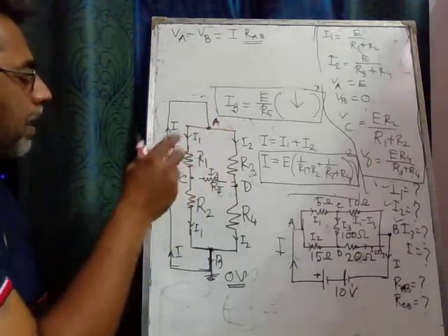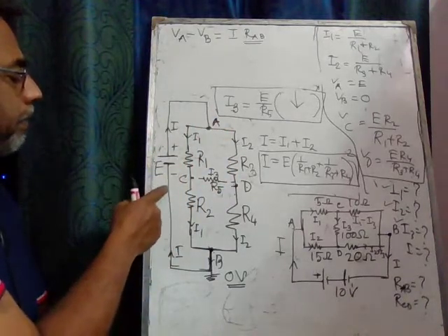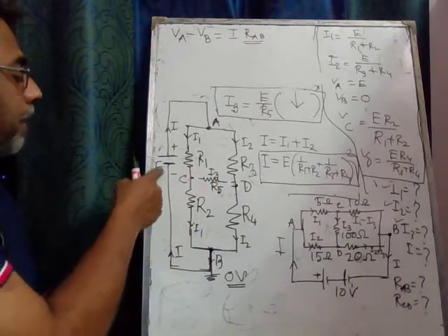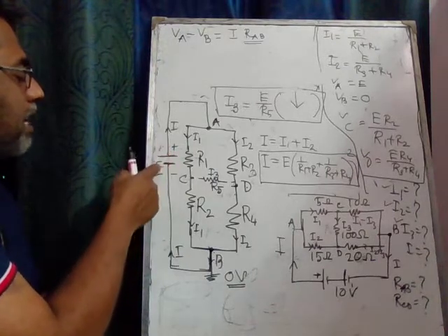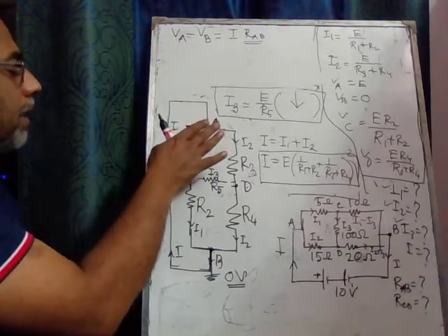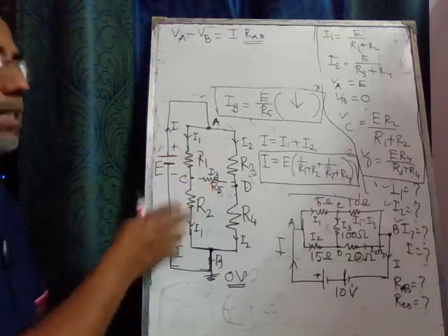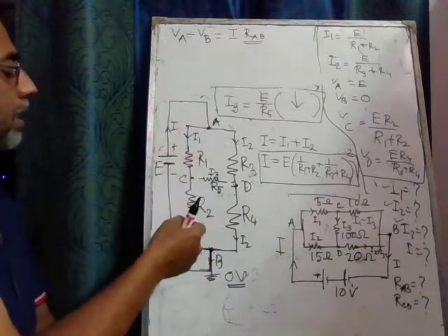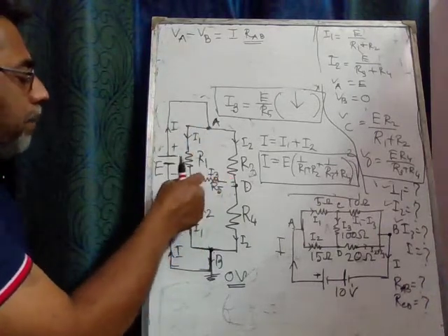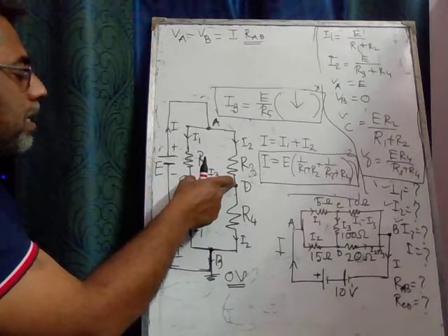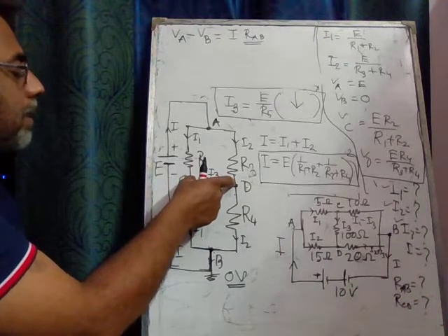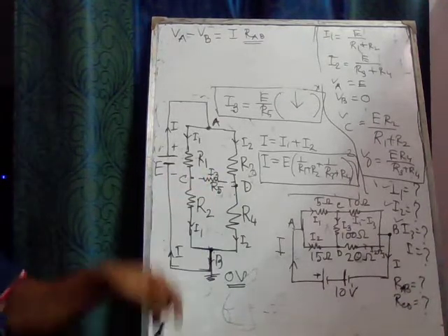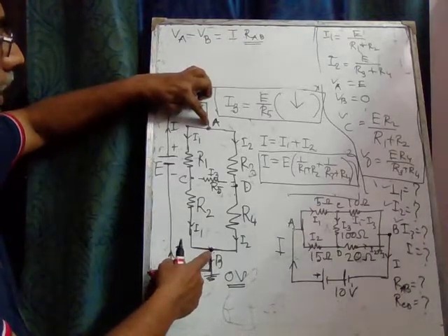So in the open circuit condition, with terminals C and D open and the battery shorted so that the EMF is 0, the circuit is left with only the 4 resistances between the points A and B. So the effective resistance should come out as the combination you are looking at here.